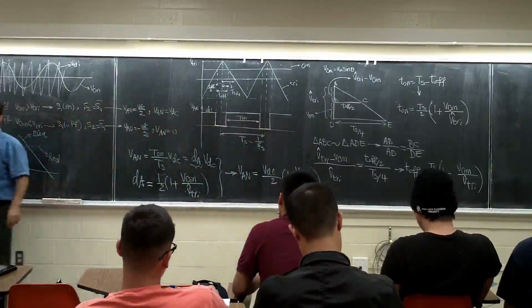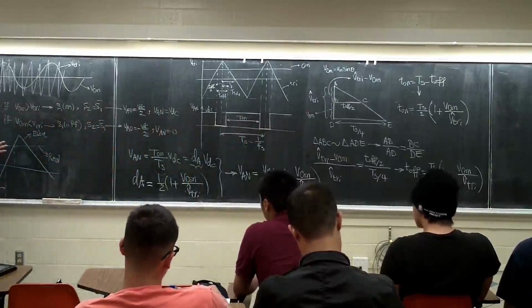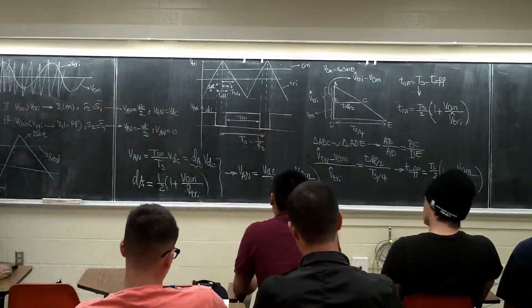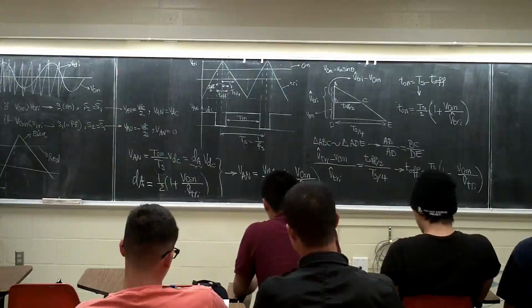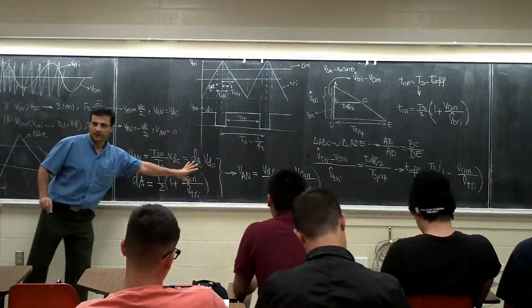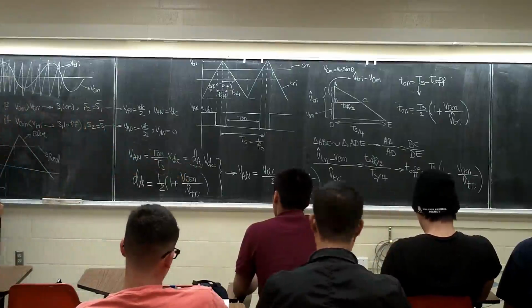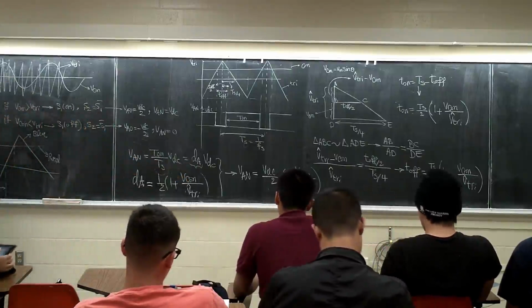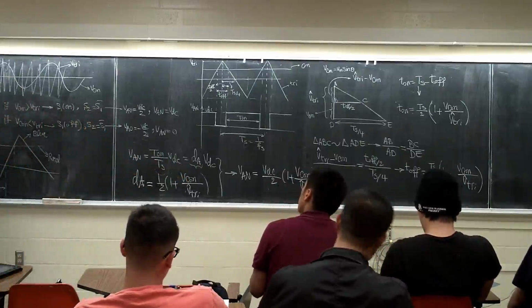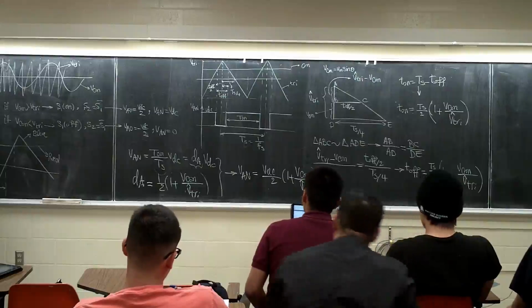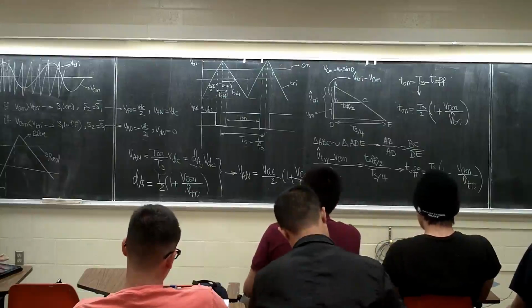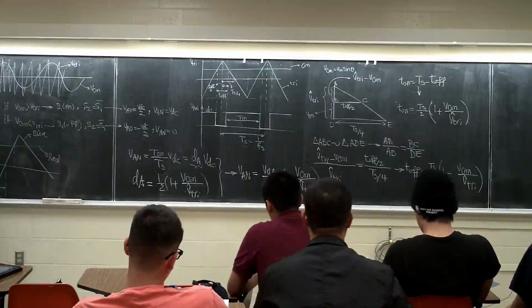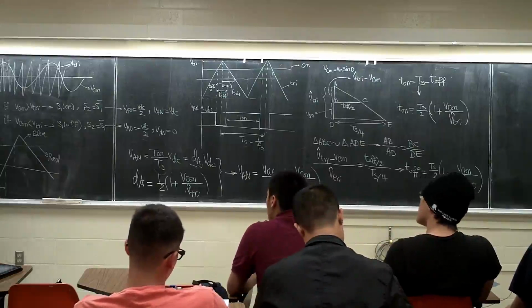Keep this one. This is not what we want. This is VAN. In a half bridge, see, this is general. What I did here is general. I just use this leg, right? I say this one is on, this one is off. How much is this voltage? And I don't care about this part, right? If this one is on, how much is this voltage? VDC, right?